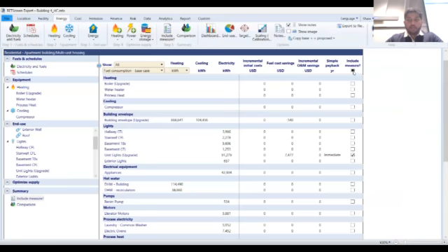Anyway, what you're essentially describing is interactive effects, right? Certain measures interact with other measures. If, let's say, you save 10 units of energy from a window upgrade and 5 units of energy from a lighting upgrade, you cannot simply add both of them together to say that you will be saving 15 units of energy. There are interactive effects, and one measure affects the other, and maybe the cumulative sum could be 12 units of energy, but it's definitely going to be less.